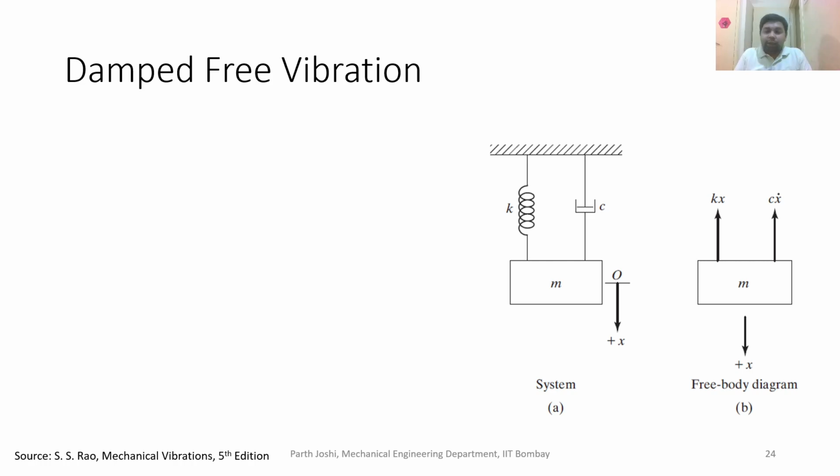So in this case, we have a simple spring mass damper kind of system. In reality, we never have a system which actually looks like this, but this is again a model of some certain system. Let us say if we have a machine mounted on a certain foundation, it can be represented by this model. So it is what is called a lumped parameter model.